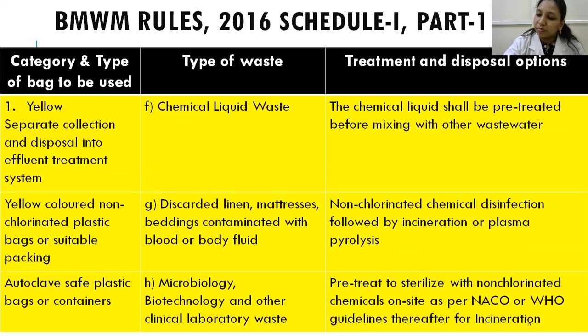And so all this waste you should not throw into bags, but there should be a separate collection and disposal into the effluent treatment system. These chemicals, all whatever the secretions or aspirations, they have to be pre-treated before mixing with other wastewater. First you have to treat them, and then you have to mix with other wastewater. You cannot just dump into the regular sewage.